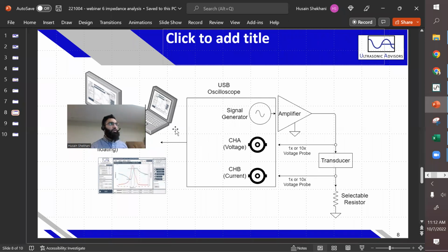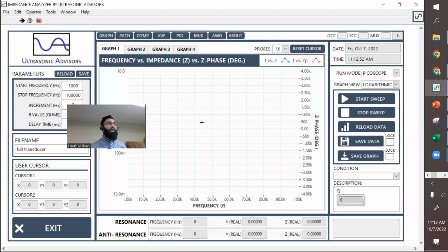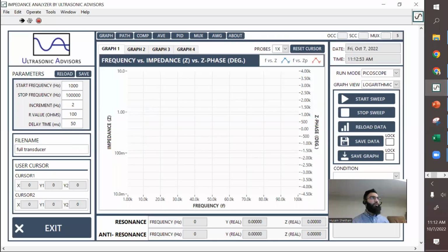Therefore, I can calculate the impedance using a custom LabVIEW program, taking this data and applying Fourier transforms to get really accurate measurements. And there we go. Therefore, I have impedance, and that's all it is. So you can practically build that, but you won't have the accuracy. That really annoyed me for a long time, trying to get the highest accuracy. Measuring really high phase angles, low phase angles and really high impedances aren't possible, but you can do what you need to for ultrasonic transducers.